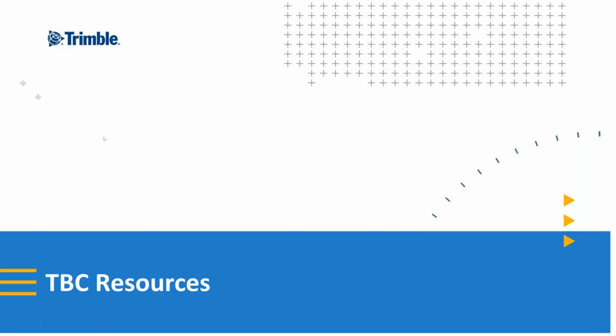you can do exactly the same thing in the vertical design. You can put different cross slopes at different locations, and it will warp the surface between those locations. So you can mimic super elevation information that you would normally put in through tables in a vertical design. But there are limitations of the vertical design for highways work because it calculates everything perpendicular to the previous string, not necessarily to the center line.